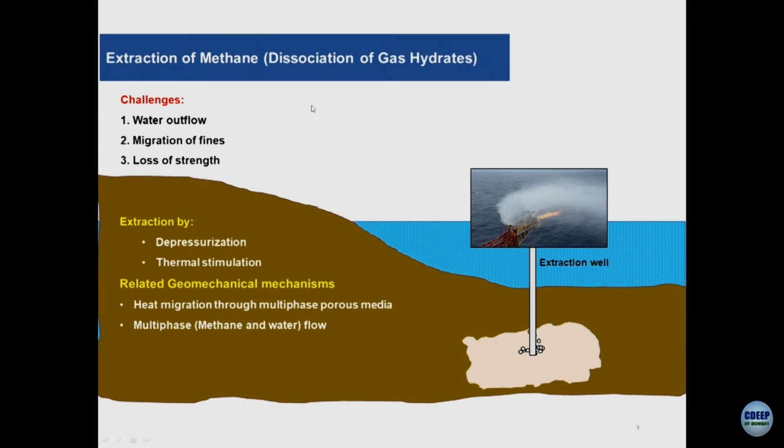So, these challenges lead to what? The first thing is that the pipings and all whatever you have installed in the system get unstable. So, wellbore instability becomes a big issue. That means, the chances are that the wellbore itself may become unstable, all the methane gas may bypass the extraction well, and then what is going to happen? It will get liberated into the environment, and if that happens, what is going to happen? Greenhouse gas. Are you realizing? So, this is a very intricate and sophisticated process. You do not want methane gas to enter into the atmosphere because of the extraction process.